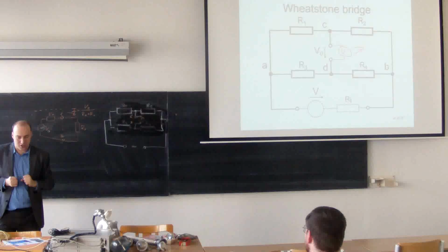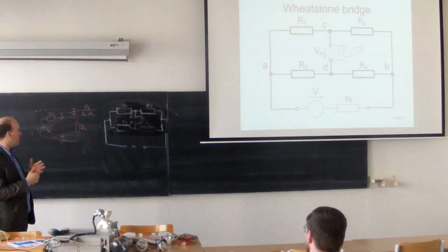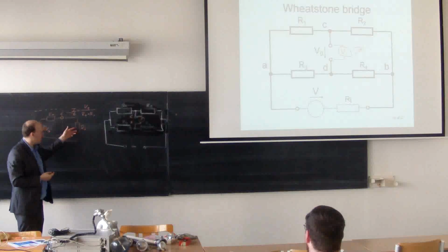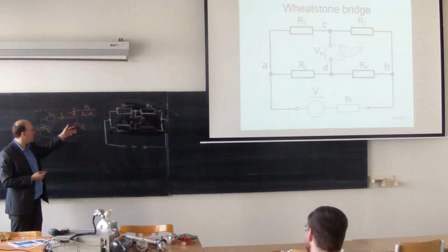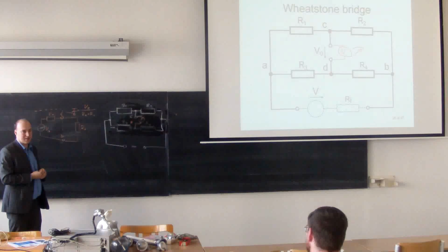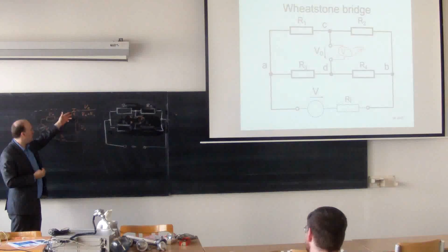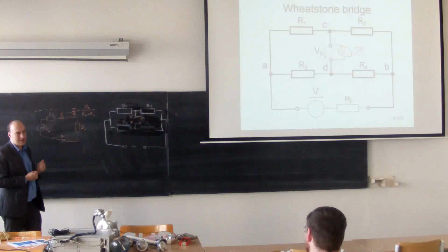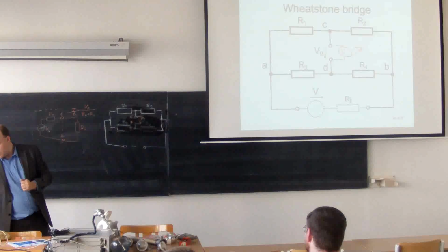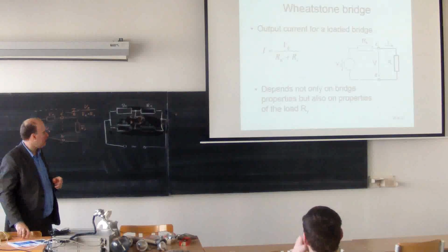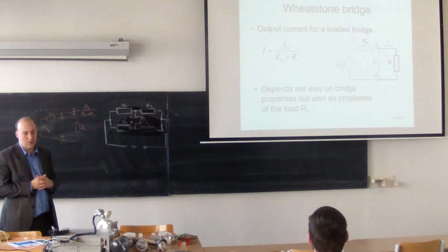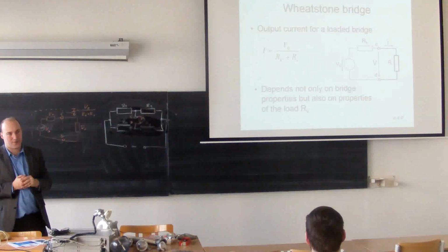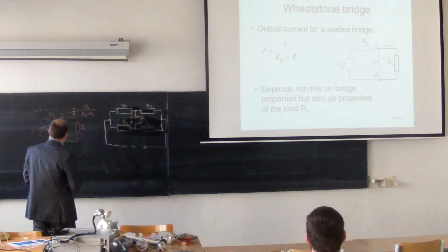So for a bridge connection, it's quite important to select a good voltmeter with some known value of internal resistance. Because then you have different readings for different voltmeters. So the result really depends on the value of what instrument you use. So that's one problem.